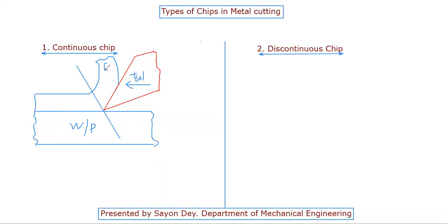Basically, continuous chips start rotating with a tool, and if these chips hit the finished part of the work, it spoils the surface finish. So continuous chips are broken by providing chip breakers. And if we take an example of drilling, the chips are broken by providing a back feed. And high back rake angle provides less resistance to flow of the chips. Hence the continuous chips are used in case of ductile materials.